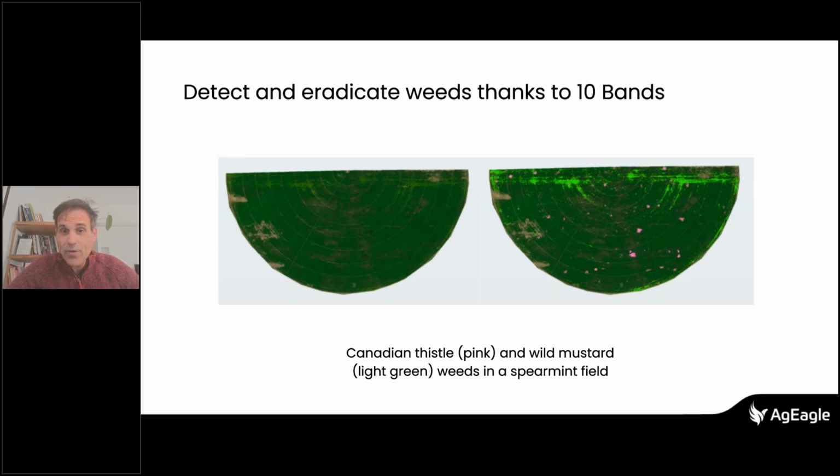If we can replace the current GPS, the DLS plus GPS we have, and replace it by the RTK of the drone, yes. So that's what I explained earlier. There are many drone manufacturers. You can either use it with the Skyport. If you work with a DJI drone, it enables directly the RTK corrected data to be written into the EXIF files of the cameras.